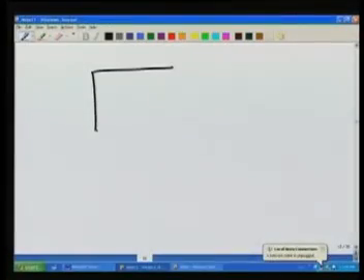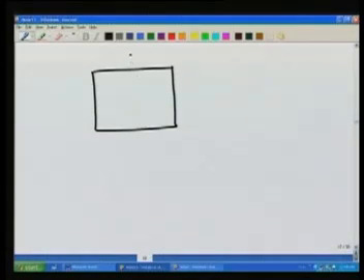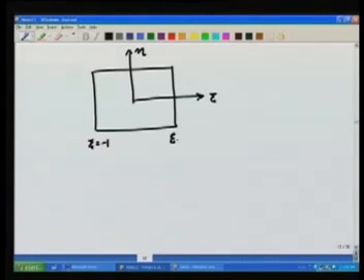How do we define it for the quadrilaterals? For the quadrilaterals, life is very easy. In fact, I have the psi and eta directions like this. You see that here psi is equal to -1, here psi is equal to +1. Here on this line eta is equal to -1, eta is equal to +1, okay. So what I do is, I take the tensor product of the 1D integration rules for the psi direction and eta direction,